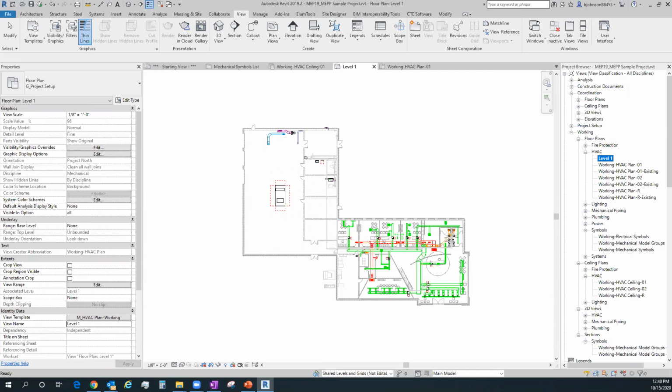If you get to 5,000, I might even do an all stop at 5,000 just to say, hey, clean all this stuff up, make sure that your warnings are taken care of. As soon as you get it down under 1,000, let the team start working again, but still have one person trying to go through and fix the warnings as much as possible. Mark values, don't really care all that much, right? If it's type mark values, probably want to fix more of those if you have more than one of the same type mark value in each family, because the type mark should be different.